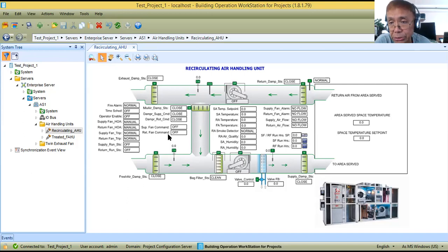Now you have to specifically tell the electrical engineer responsible for the motor control fabrication that in this MCC, for this recirculating air handling unit, I need BMS points. These are the BMS points. For control or the start and stop, I can allow 24 volts. But for the monitoring points such as handoff auto, run, and trip status, I need volt-free contact. Volt-free contact means there should be no voltage present in the contact, because this contact will just open and close. So be sure that the points are volt-free contact.